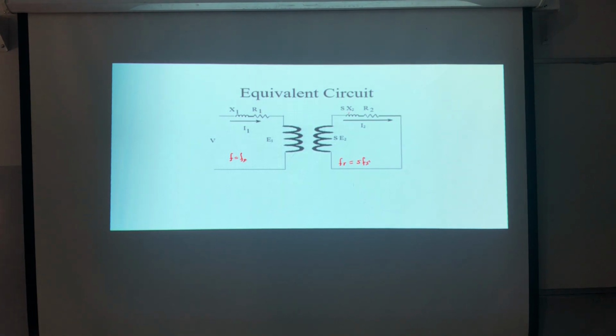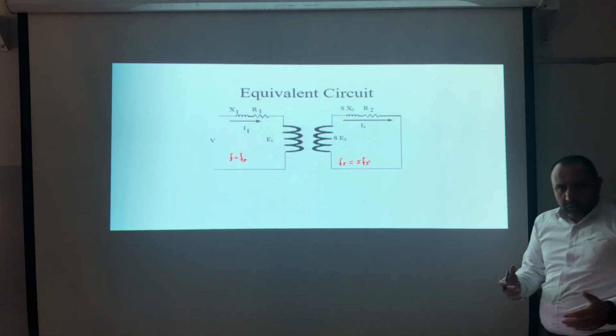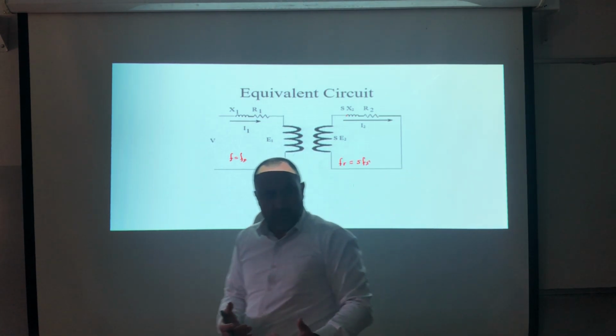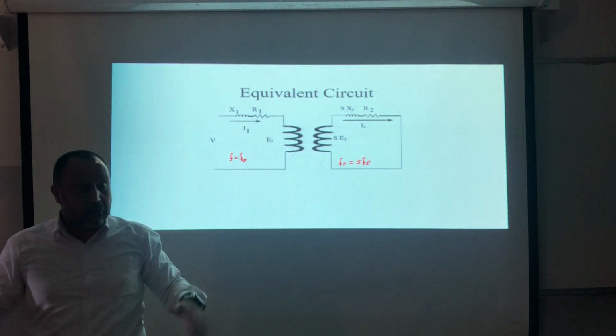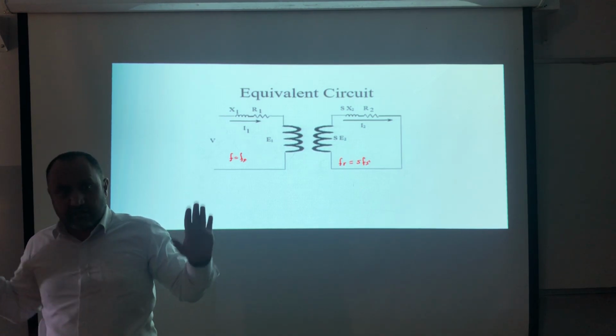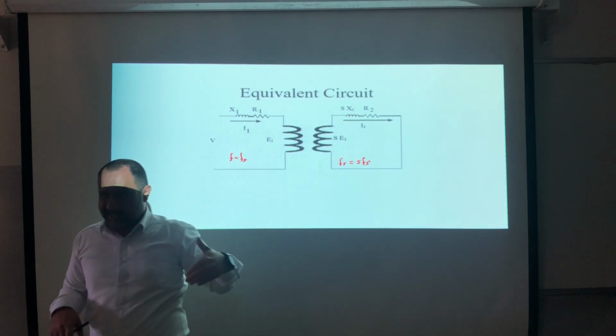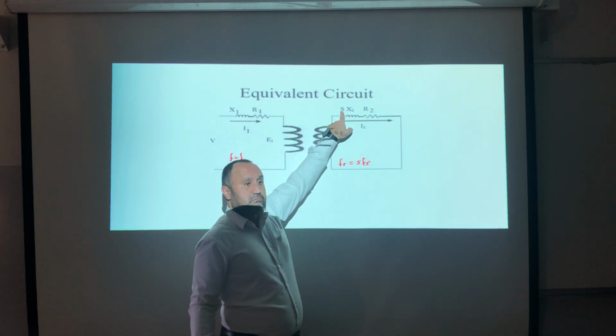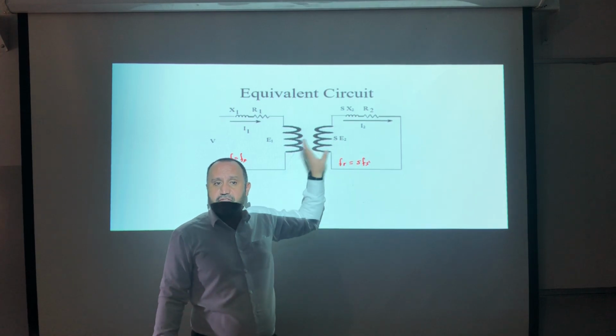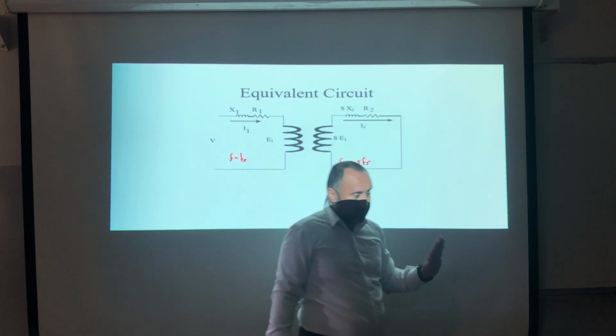So in this case, if I need to use the frequency, you know that if I'm giving you any inductance, it will be given according to the frequency. So in general, we will give the frequency of the stator. Yeah? So here, because the frequency is s fs, here I will have s here. And the same thing here for the induced voltage.